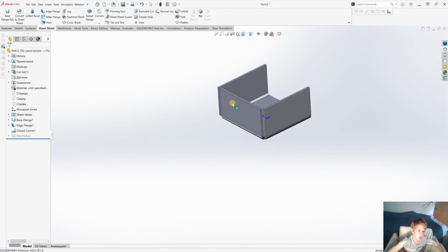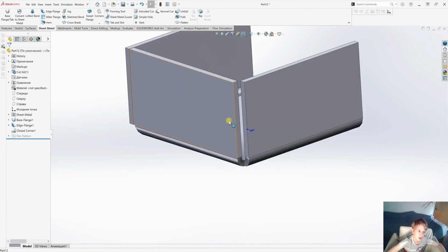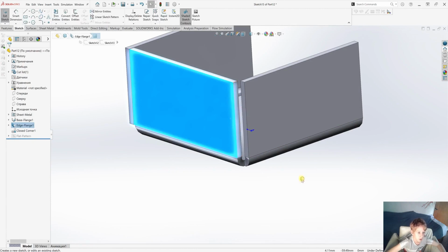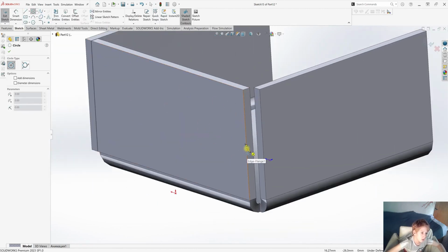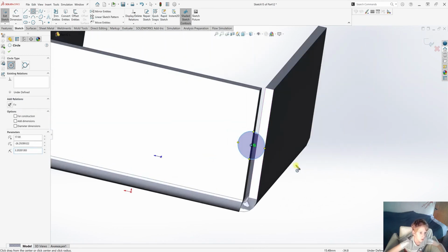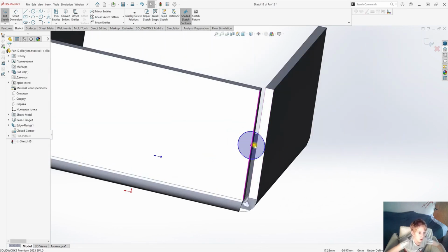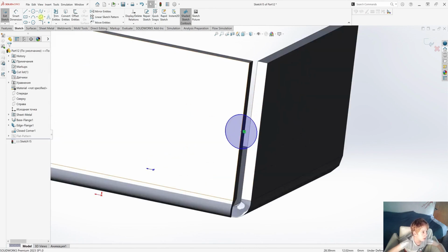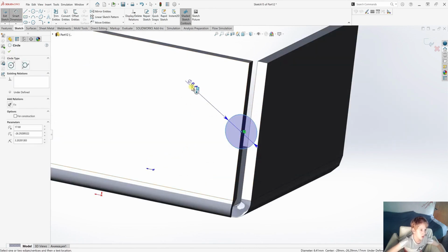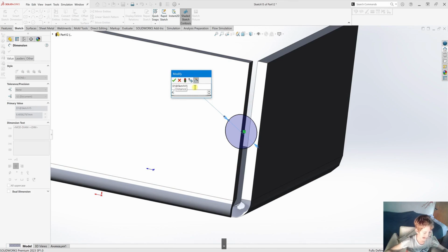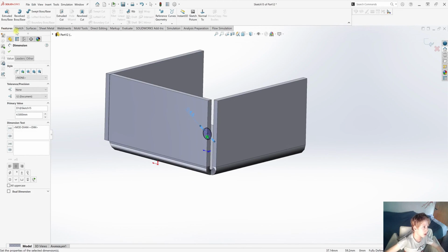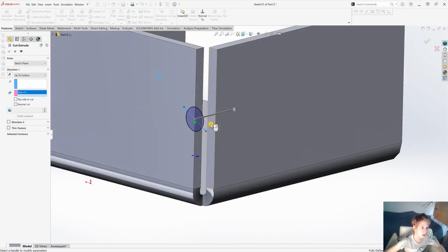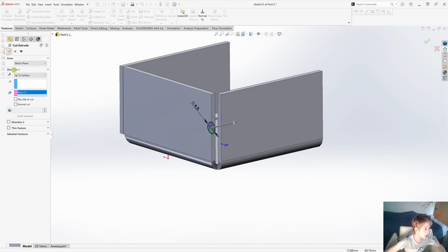Now I'll show how the corner command works with a surface cut. We draw a sketch on this surface. A circle from the center. We see that a midpoint relation has appeared, and we make our circle, which is about 4.5 millimeters. We go to the features option in the toolbar and extrude up to our surface. Okay?